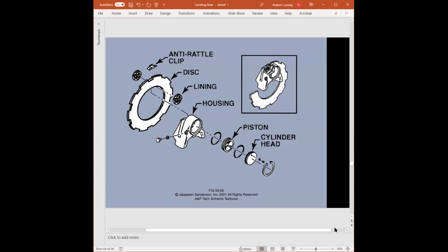This is really just a breakdown of a floating disc system. The brake lining, kind of the important part on this is this. Unlike the other brake linings that are riveted to, say, a plate, the linings or pucks generally for a fixed caliper floating disc are not physically attached to the piston or any type of plates.